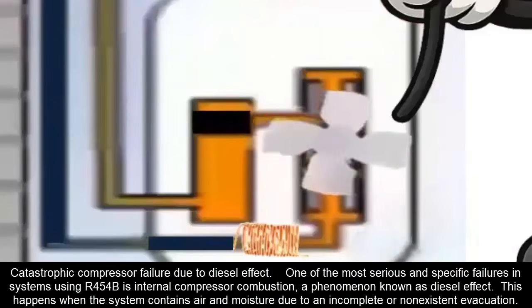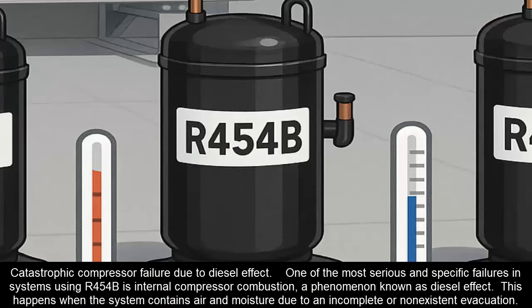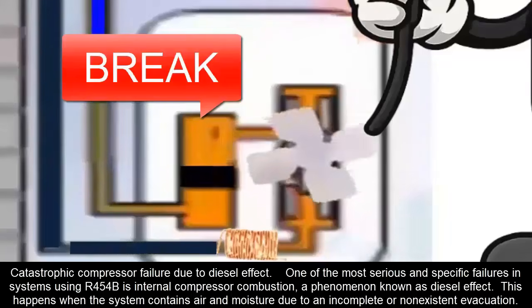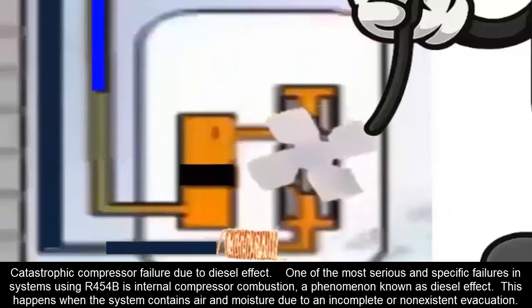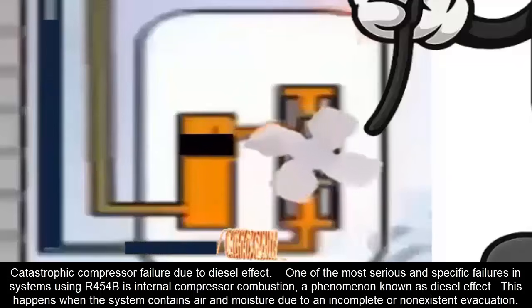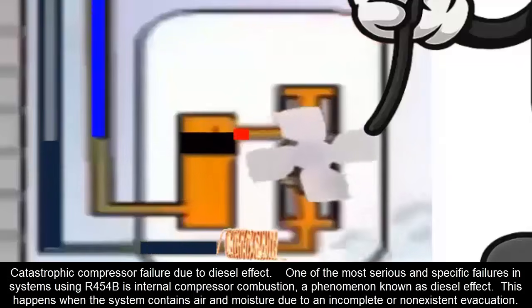Catastrophic compressor failure due to diesel effect. One of the most serious and specific failures in systems using R454B is internal compressor combustion, a phenomenon known as diesel effect. This happens when the system contains air and moisture due to an incomplete or non-existent evacuation.